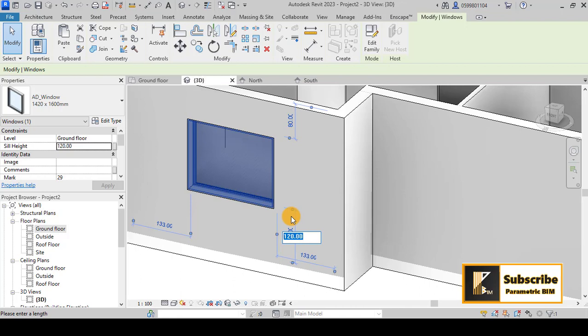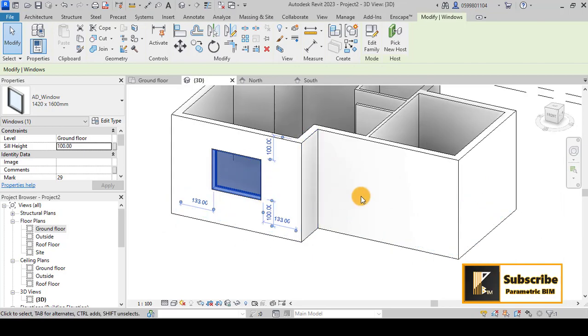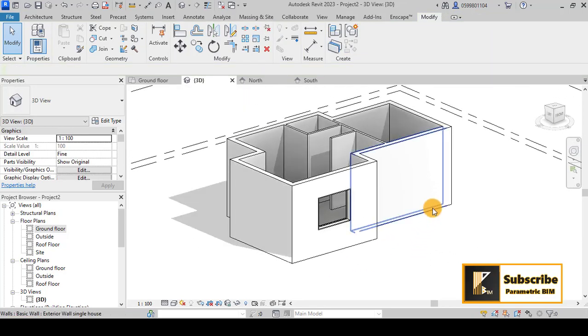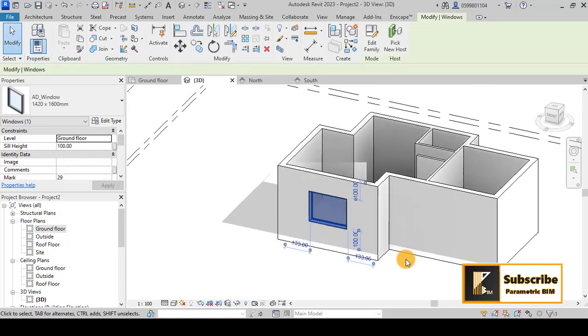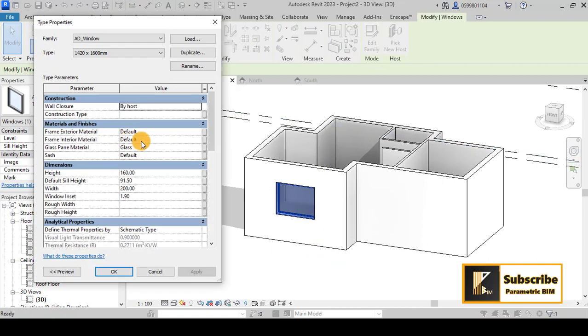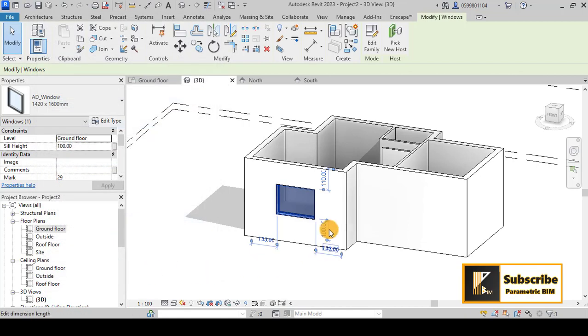And also you can change it from this temporary dimension parameter. For example, if I put maybe 100, you can see that the window came below. So this is the way if you want to modify the windows and the dimension of windows. Also you have the opportunity maybe to change the height of the window. Maybe I want it to be 120 or 150, let's say. So once I click apply, you can see that it will be changed.